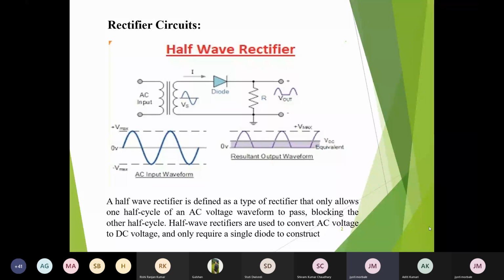That unwanted part present at the output is called a ripple. So ripple is a component of the AC signal that is coming from the input side at the output. At the output of the rectifier, we always want a maximum DC signal to observe across the load resistor. But the rectifier circuit alone is not sufficient to convert AC into DC form. Now we are going to see its working.